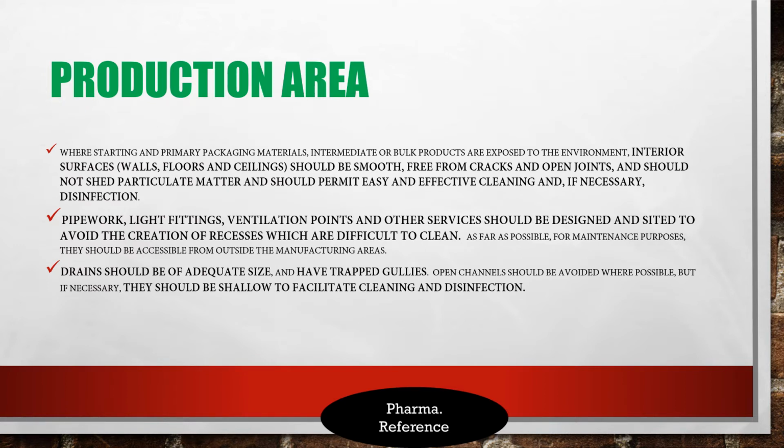Production area, where starting and primary packaging materials, intermediate or bulk products are exposed to the environment. Interior surfaces, walls, floors, and ceilings should be smooth, free from cracks and open joints, and should not shed particulate matter, and should permit easy and effective cleaning and, if necessary, disinfection.